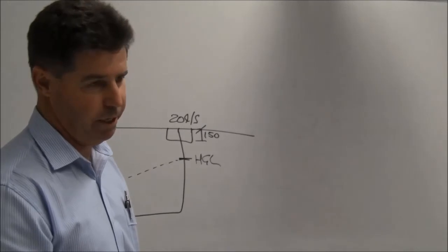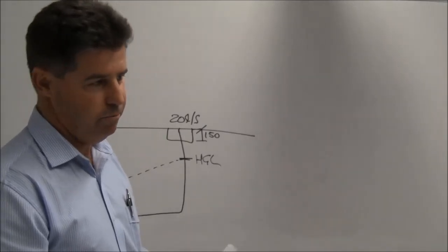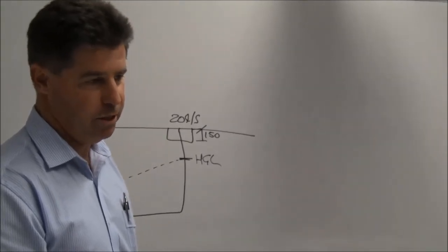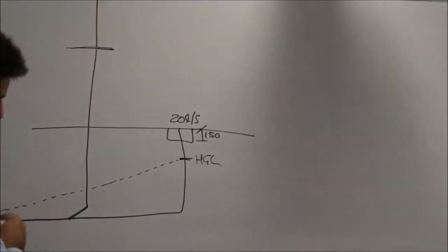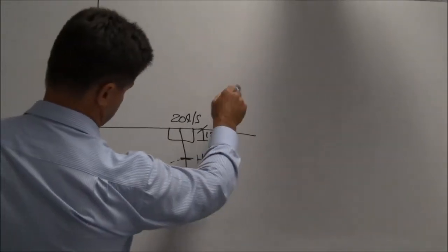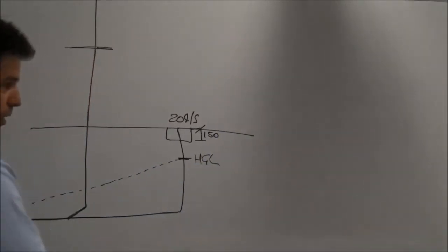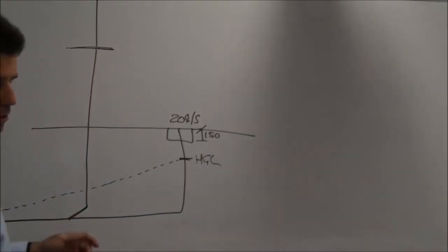So possibly increasing pipe sizes is where you would start. And obviously as you keep going down the system towards the outlet, normally the hydraulic grade line works in reverse. So when you're designing a system, it's normally at the head of the line working your way down to the outlet. Hydraulic grade lines work in reverse.